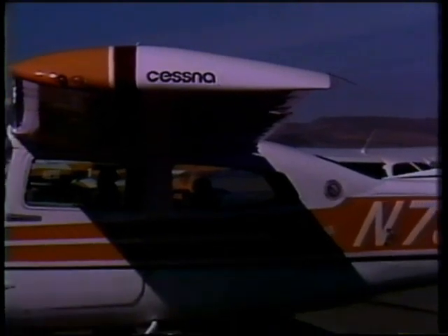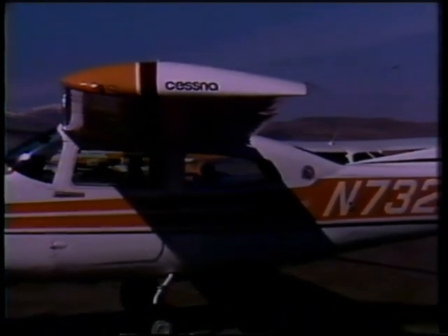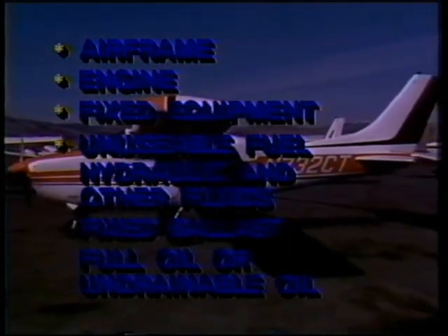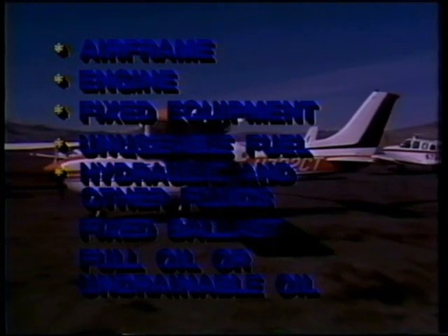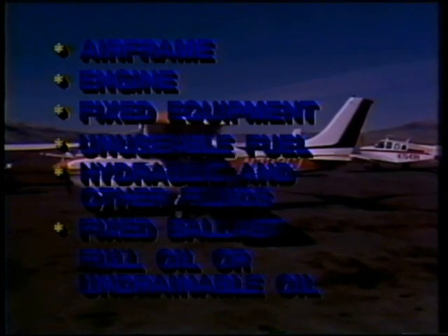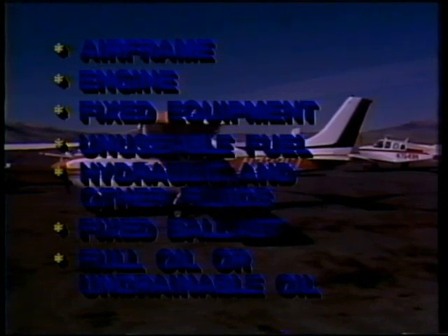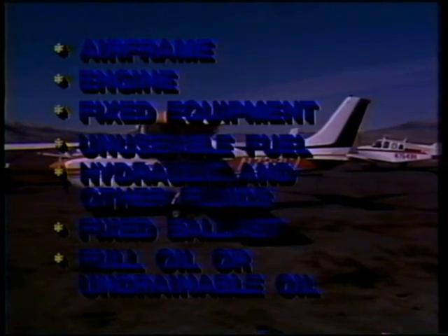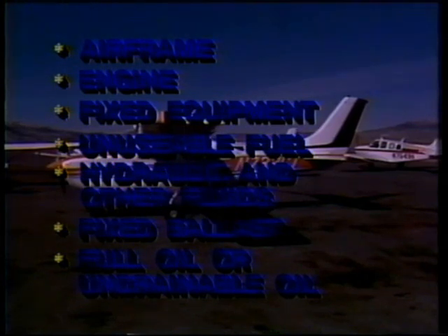The empty weight is the weight of the airframe, engine, fixed operating equipment, unusable fuel, hydraulic and other fluids necessary for flight, fixed ballast, and full oil on aircraft certified after March 1st, 1978.